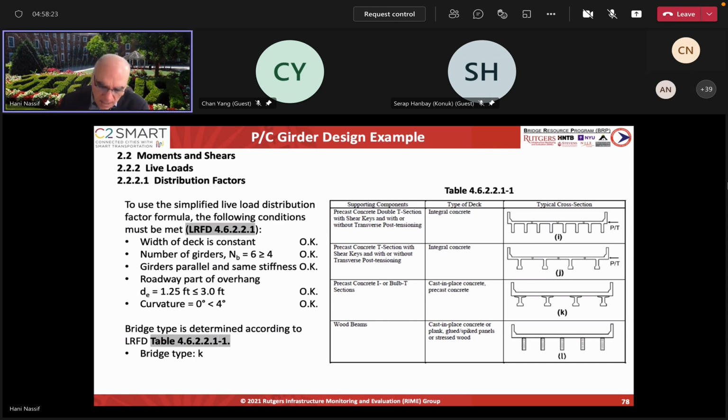What's the deal? Yeah. So, for example, if you have a 3-lane bridge coming into a 2-lane, usually what they do is put a variable spacing, right? That's what I think you're referring to, isn't it? In other words, it's not a constant width of the deck, and the spacings are not constant either. It's in a fanned arrangement. One end is one spacing, the other end is the other spacing. So how does that work on these formulas?